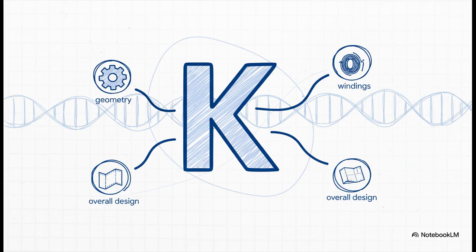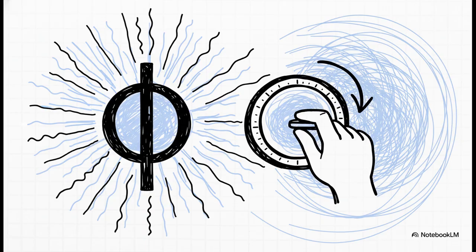It basically bundles up all the physical design choices. The core's geometry, how many turns are in the stator windings, how they're laid out. It's basically the machine's DNA. To that, we add phi. Phi represents the magnetic flux per pole. You can just think of this as how strong the magnetic field coming from the rotor is.